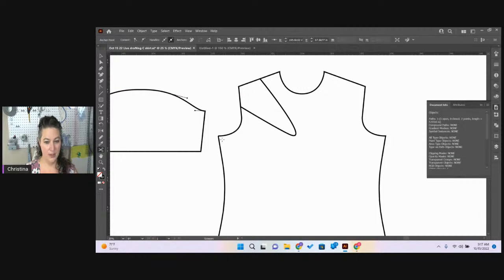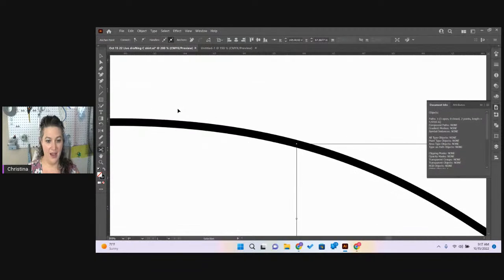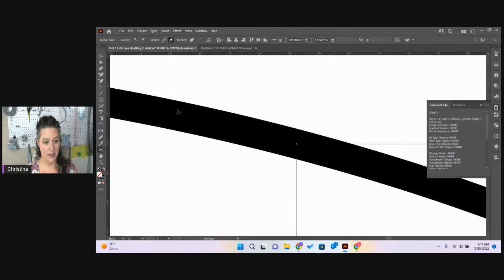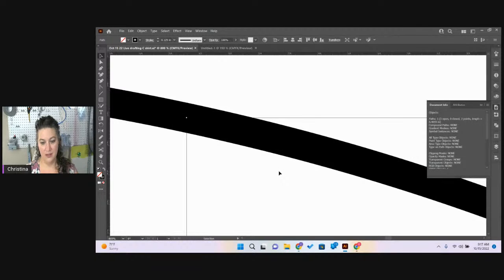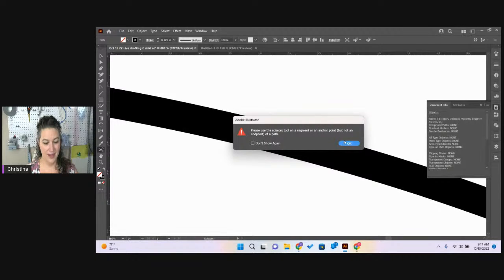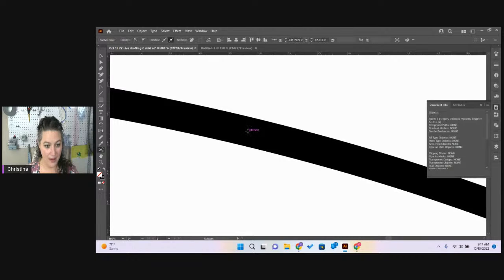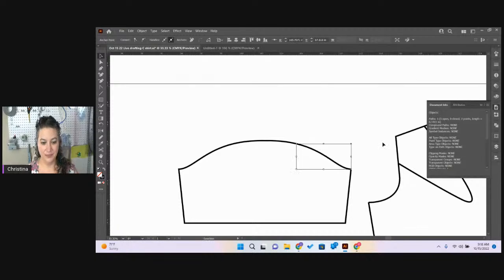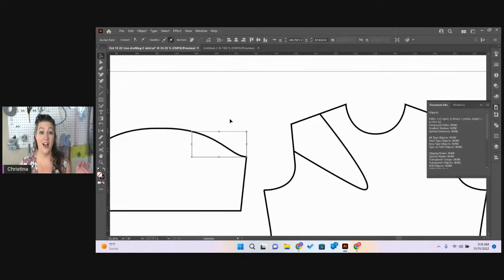So we're going to do another one. Boop. 5.9. So now I'm going to zoom way in because I'm real close. I'm going to X and I'm going to Control, cut. 6.4, too far. Undo, cut. I was right on it, not quite. 6.1, perfect, there we go. So that's going to give me that notch of where I'm going to be cutting it in the front.